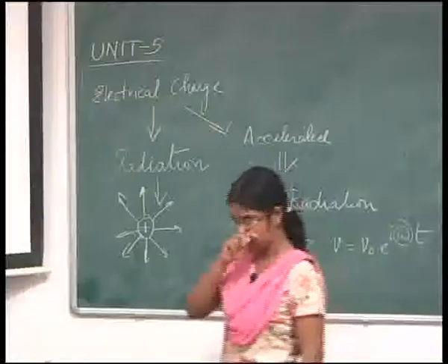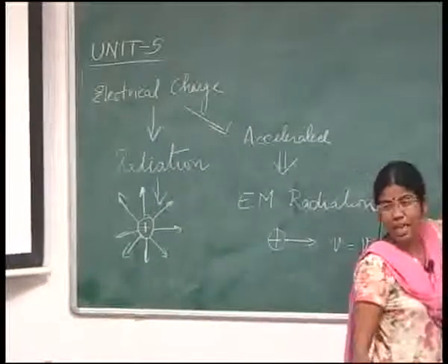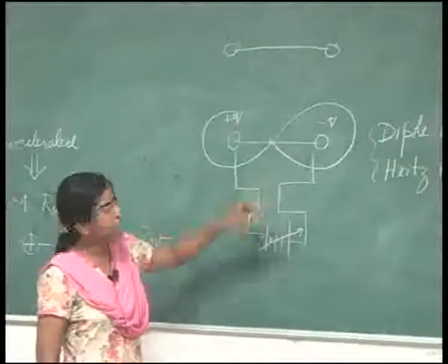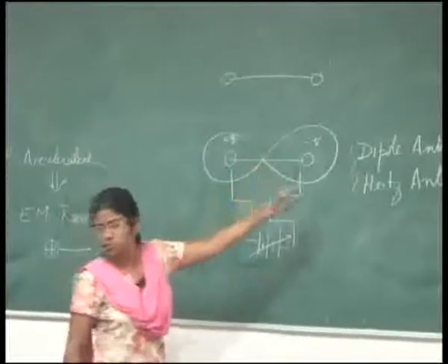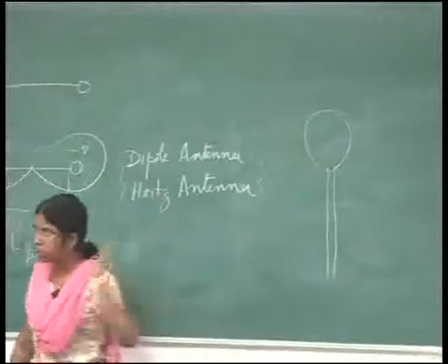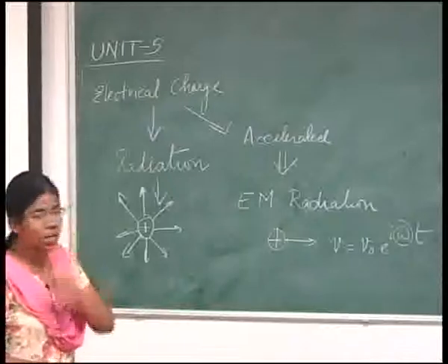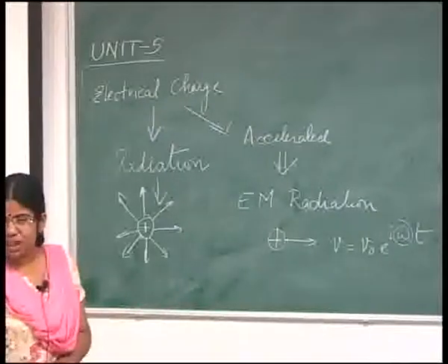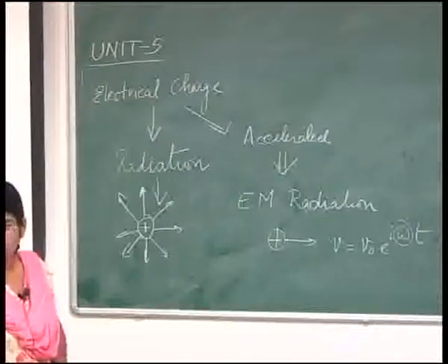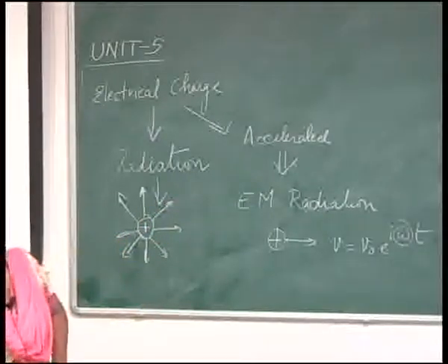So, what does that mean? It means that the radiation here I have in two directions. This is the radiation pattern, and these are called radiation lobes. So, this is more or less an omnidirectional antenna, because here radiation is only in one direction. So, what Marconi used was an omnidirectional antenna, and these antennas are still used in wireless communication. Most small-range wireless communication uses Marconi's antenna, or monopole antennas.